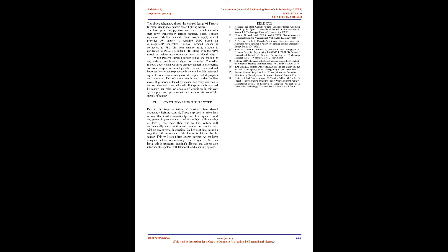In the controller block, the Arduino is programmed in such a way that when a person enters or leaves the room, the controller performs various tasks such as comparing, time delay, occupancy in the room, then observes and validates the operation and sends a signal to the 4-channel relay module. As we are controlling 4 light fixtures, we are using a 4-channel relay module which controls the switching, on/off, of the light fixture, therefore the cycle repeats itself and operation will be continuous.